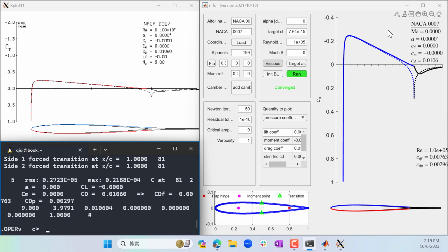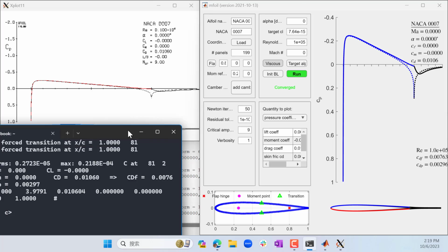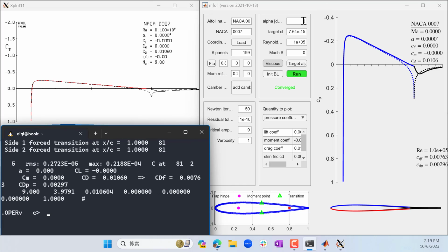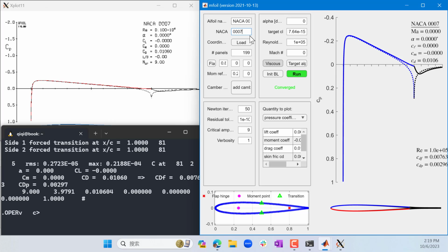Yes? So is that the displacement thickness we talked about last day, is that pressure multiplier? Exactly. The displacement thickness we are talking about today is exactly that. The displacement thickness is how much the existence of the boundary layer displaces the streamlines outside of the boundary layer. So the effect here is to make the airfoil appear as if it is thicker and therefore has a lower pressure.